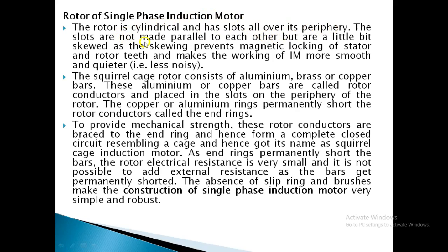The slots are not made parallel to each other but are a little bit skewed, as the skewing prevents magnetic locking of the stator and rotor teeth and makes the working of the induction motor smoother and quieter. It means it reduces the noise.